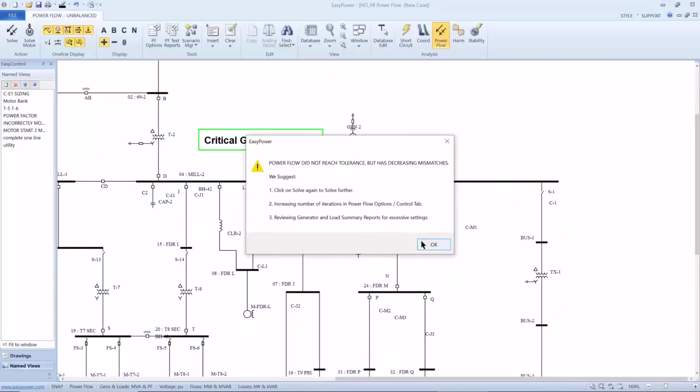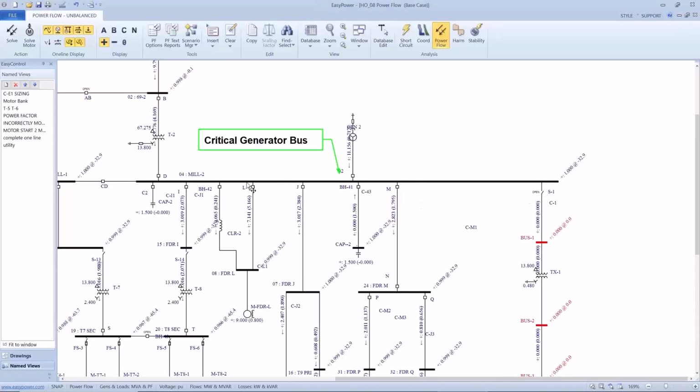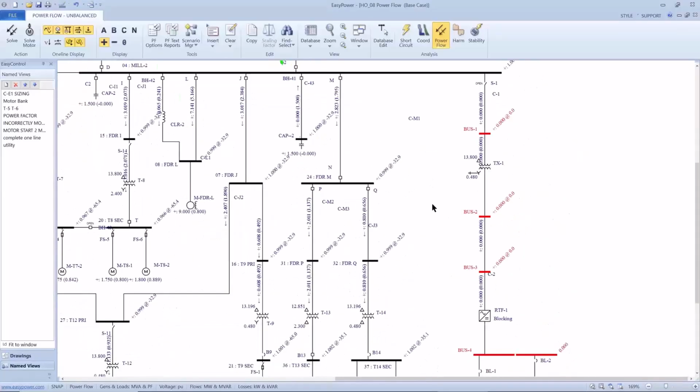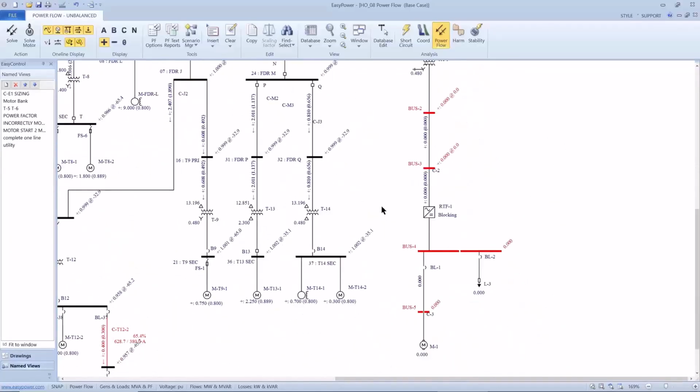One of the error solving techniques is to isolate all the breakers on that bus and then close them one at a time until you find the one that's busted. So that's why I know everything's working as long as that breaker or that switch is open. If I go down here and see what else is going on, I can see I have a load, I have a rectifier, and the other switch I have down here is this load switch.